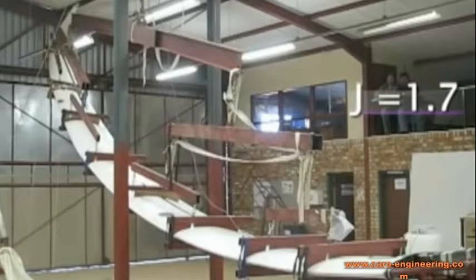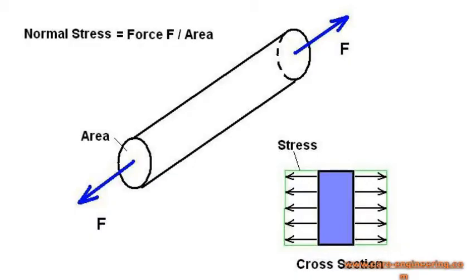We have to deal with different types of stress on an airplane. The simplest one is normal stress. You get this if you take a rod and pull on both ends with a force of, for example, 40 pounds. The stress in the rod is the same anywhere in the rod, and it is all in the same direction in tension. The stress in the rod is directly proportional to the force. It would be lower by 50% if you only pulled on it with 20 pounds.